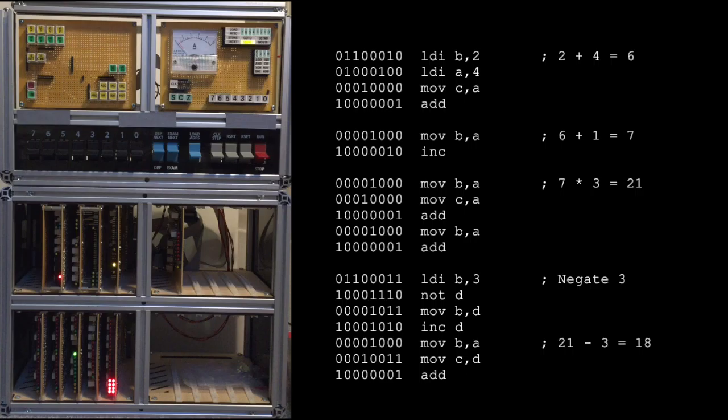Now there's quite a lot else going on, and that's because even though the instruction register has nothing in it, that is, it's all zeros, that's the instruction for copying register A to register A, effectively clearing register A of the nothing it contained. If you rewind the video a little bit, you'll see the control lines lighting up at the right times in display A.